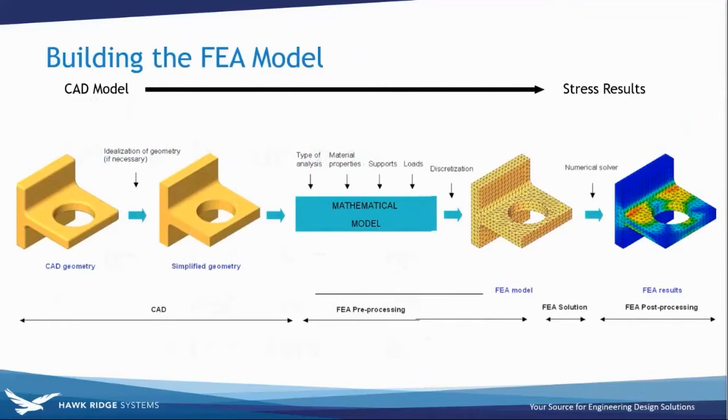If I change the model, it's going to update the drawing. When I'm making little tweaks in simulation, I don't want to mess with the drawing, so I always make my own configuration or my own unique model. Some modifications that you could do might include simplifying the geometry by removing unnecessary and small features that might be element hogs, creating split faces to apply boundary conditions to, and being able to manipulate model dimensions to run parametric